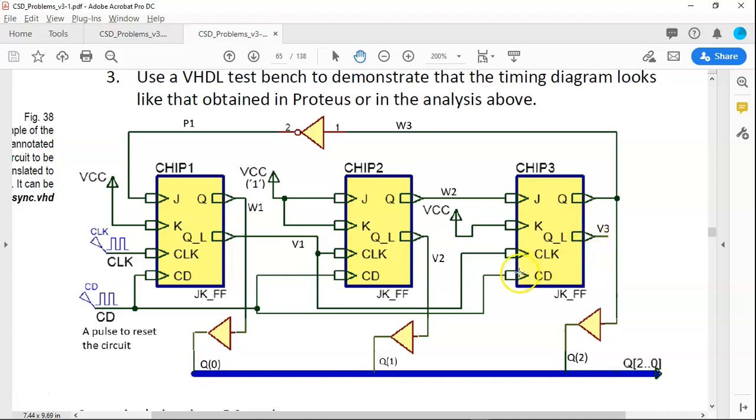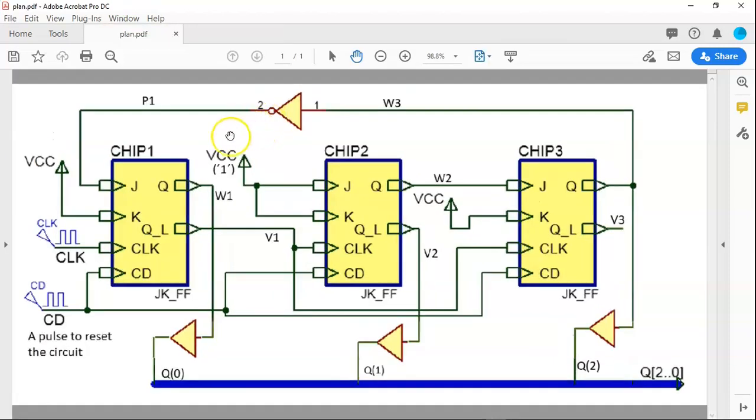All right? So you have to have this schematic very well annotated, and then you need to find the components, for example, from DigSys web. In some way or another, you will find them. All right? So before developing in VHDL, you have to have a plan like this, which is the circuit that you have in mind, now modified with some annotations for every signal.